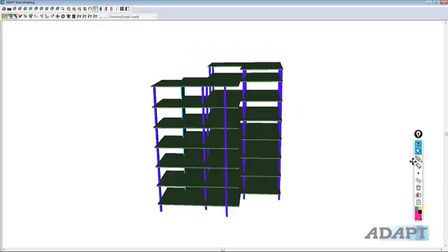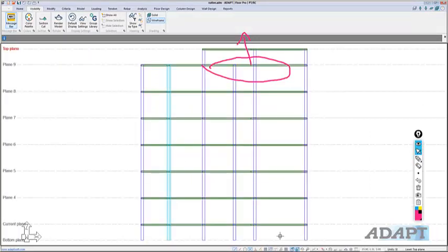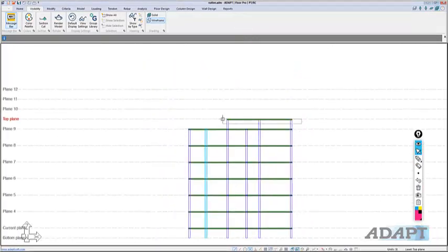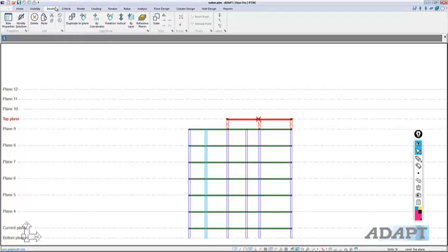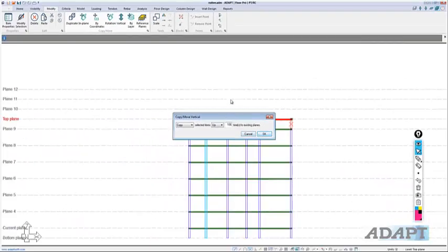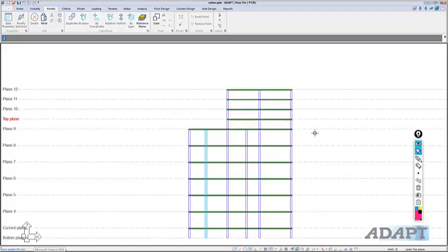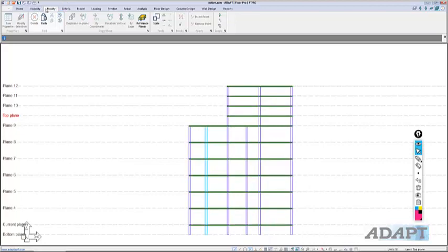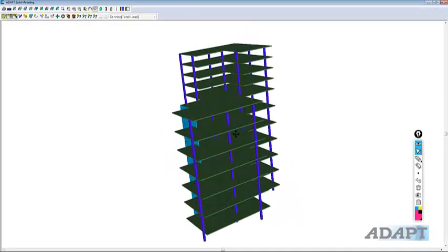And I want to copy this level now up to the remaining 2 or 3 levels that we created for the model. Okay, so I'll go back to a side view and take this. I'm going to copy this 3 times. So I'll select the option for modify, vertical copy. I'll copy this up. Even if I said 100 times, we're not replicating the level, we're copying something 2 levels. So this will only fill in whatever is in place in terms of the vertical structure of the model. And that creates those additional levels. And finally, we end up with something that looks like this.